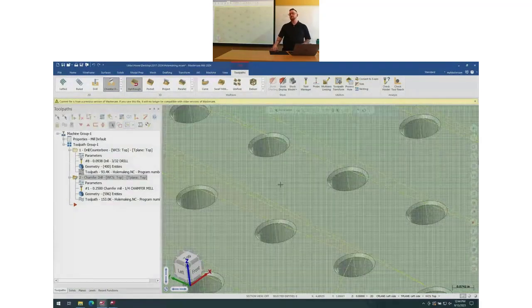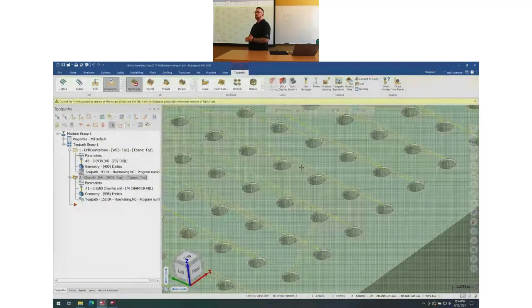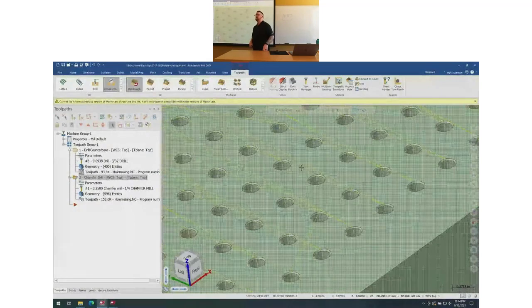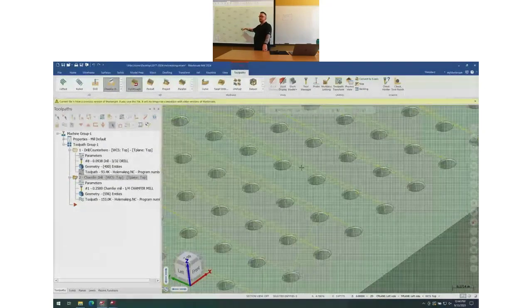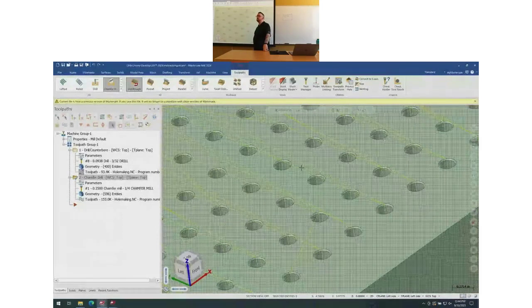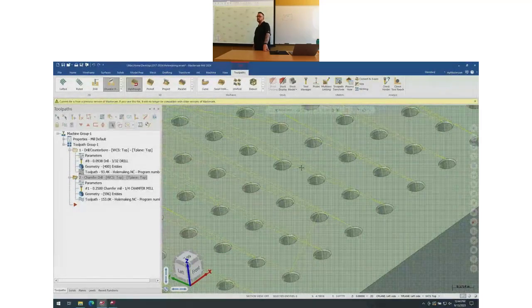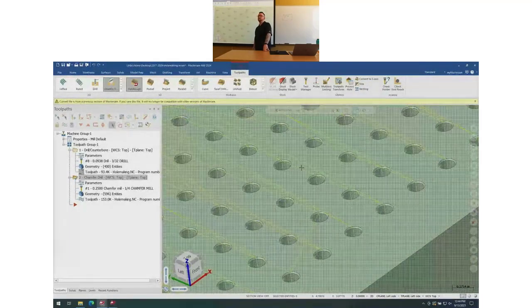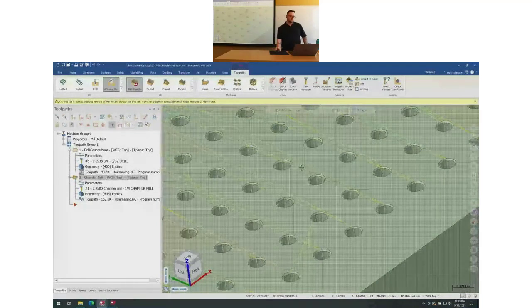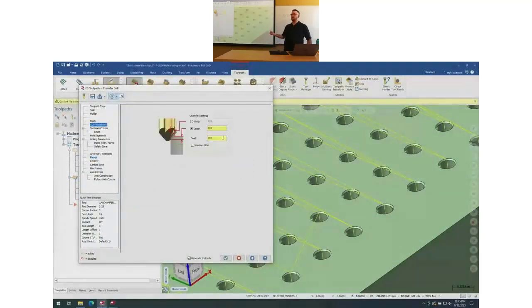Are you using a multi-flute countersink, or are you using a chamfer mill? I'm actually using a chamfer mill for that because these all happen to be 45 and 90 chamfers, so it makes more sense to do it with that tool. Right. It makes a great chamfering tool. For countersinking your hole, it works really well because you've got the extra flutes. You might consider using a little bit of dwell just to make sure it's nice and clean, which is an option in the cut parameters.